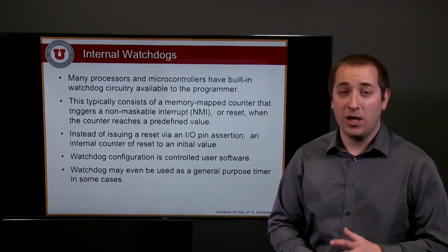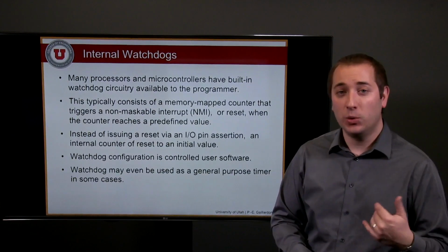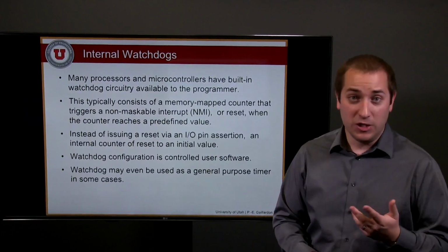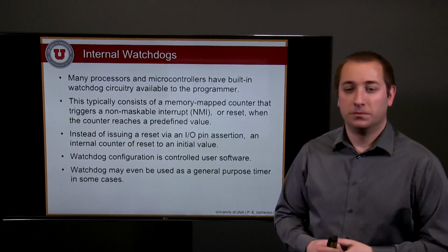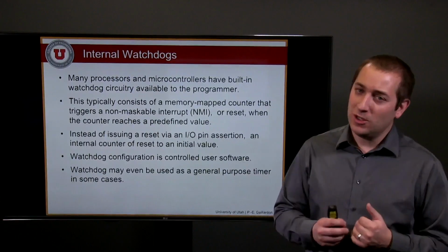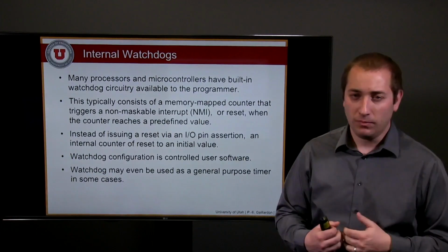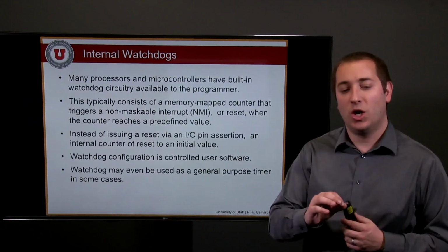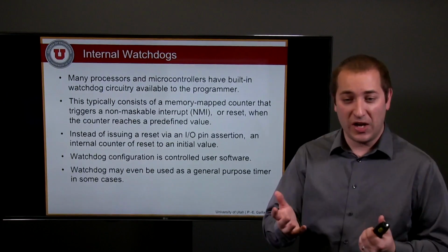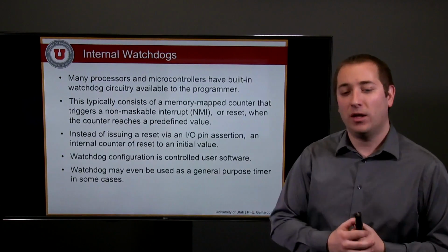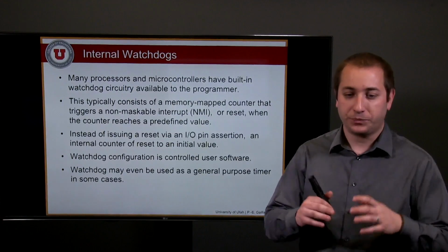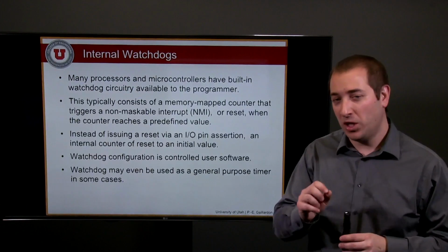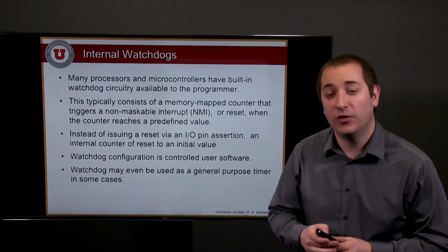It is possible to find both external and internal Watchdog timers. External Watchdog timers are totally separate devices that count time and that will activate the reset line on your MCU if need be. Internal watchdogs are built-in circuits within your microprocessor or microcontroller, and are available to the programmer at a very low cost. They typically are mapped to an NMI or the reset, and trigger it when the counter reaches a predefined value. Your watchdog will be controlled by a user interface, so you have a special instruction to reset this timer.